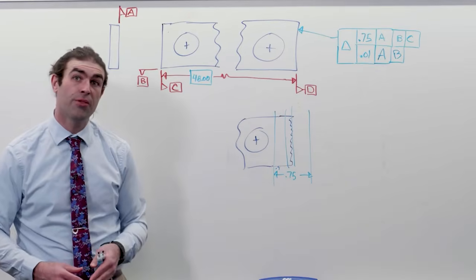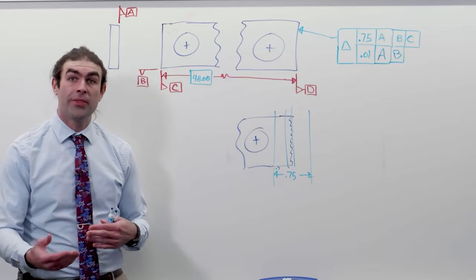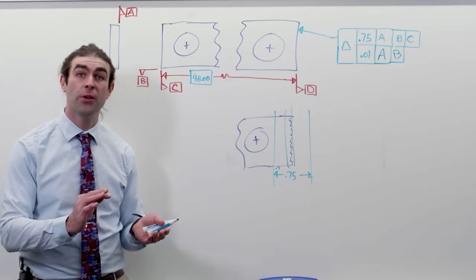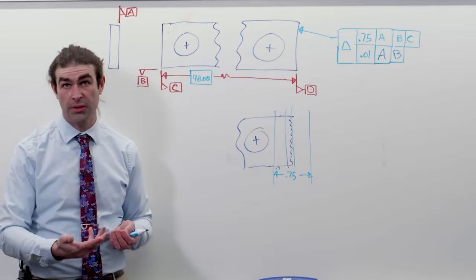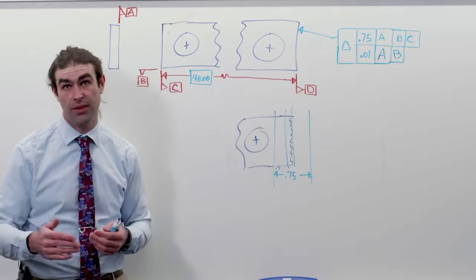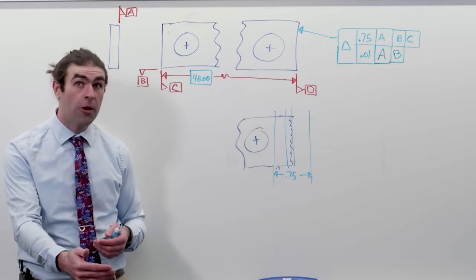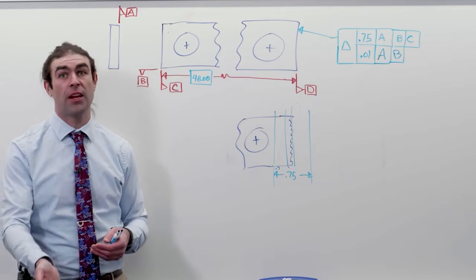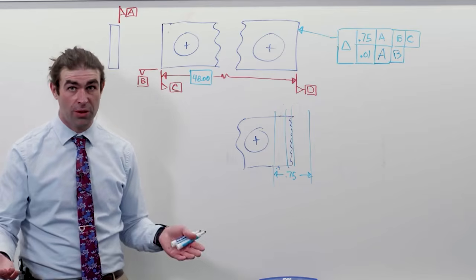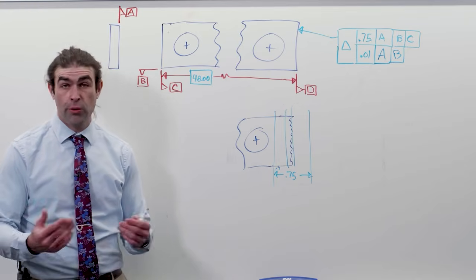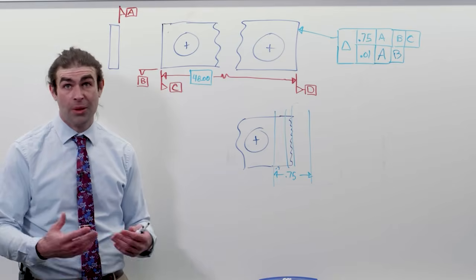And if I didn't mention it before, the difference between the composite and the two single segments is essentially nothing in this case. With the two single segments, you can have the datums in a different order if you needed that for some reason, whereas the composite, they need to be in the same order and the same material condition. So if it's a different material condition, it's a different datum reference frame because you're calling out the datum in a different way. So that's it for this video, just an overview of Profile and some of the applications.